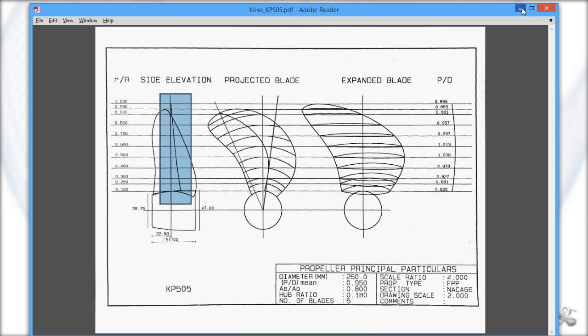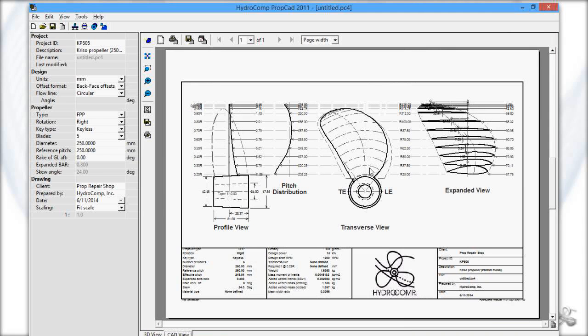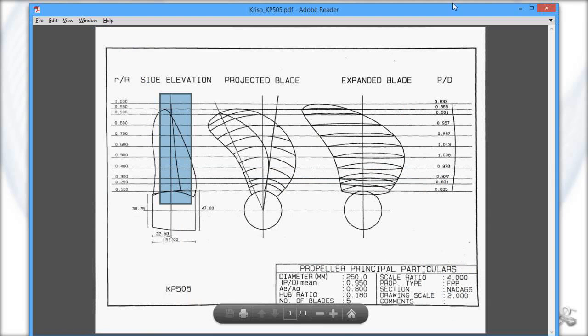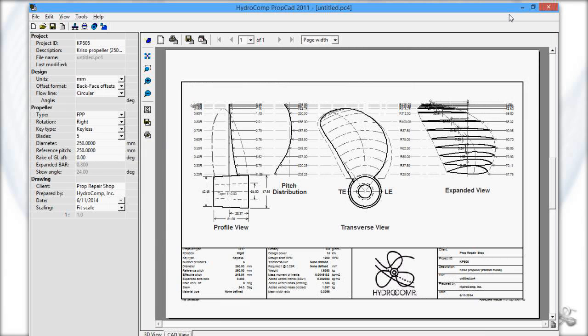A lot of this is due to our simplified skew distribution. We can see the cubic here, it goes up and then to the left. There's no positive skew angle on the leading edge, but we know that we actually do have positive skew here. So what are we going to do about this? Well, basically, we're going to manually edit the section data.